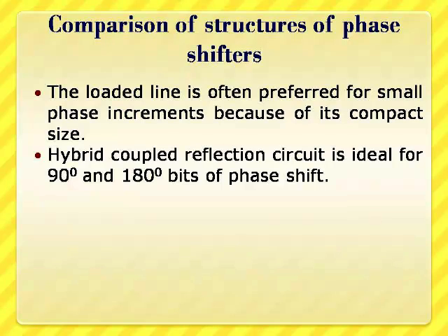The PN diode is mostly used in all these types of phase shifters. It is a popular choice, but there is an alternative for us. The varactor can also be used as a switch. It is capable of very rapid switching, but its average power handling capability is limited. As a special case, let us see something at this juncture.